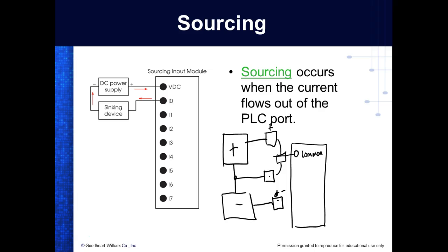So it brings in Alabama Power, TVA, 120 volts, runs it through a transformer, steps it down to make it safe, runs it through, generates a plus and minus DC power supply, and now we can electronically regenerate what? AC. But now I control the amplitude and I can control the frequency. Just like your car radio. Your car radio speakers will burn up if you put DC on them. So what does your car radio do? It takes that 12 volt battery, somehow it generates a plus and minus DC out of that thing, and that's what goes to your speaker.